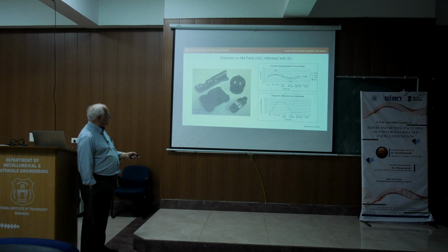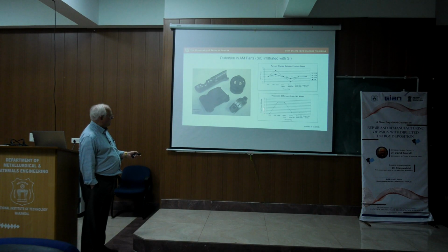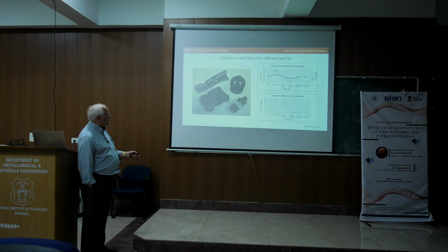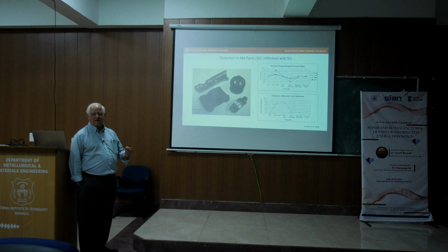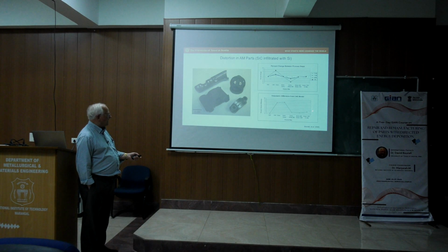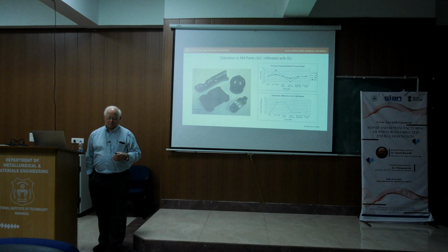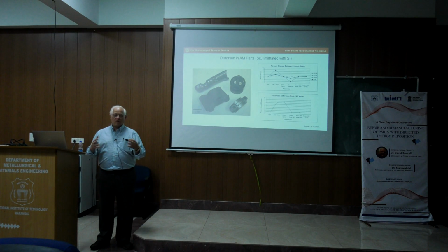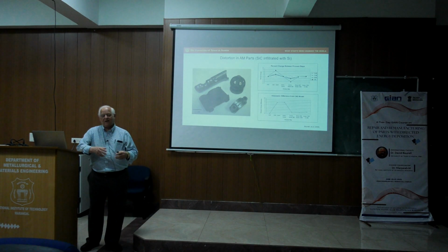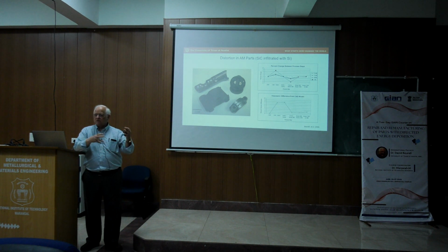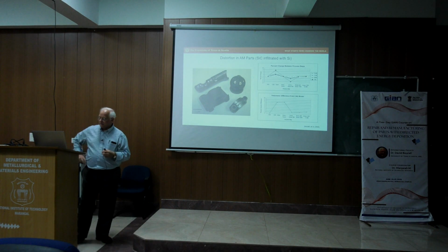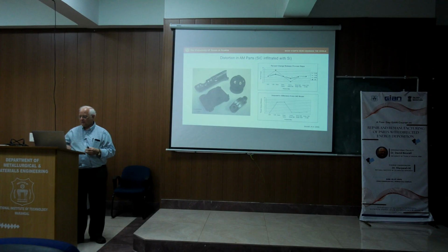So the bottom here shows the percent volume change as we go through. And again, this is relative to the CAD model. So we expand when we build the part, and we shrink when we do the burn off. And so we have quite a bit of part that's in very good shape. So the point is that as we do the builds, regardless of what the additive manufacturing process is, and do the post-processing, we can get shrinkage and expansion that may or may not have an impact on the quality of the part.